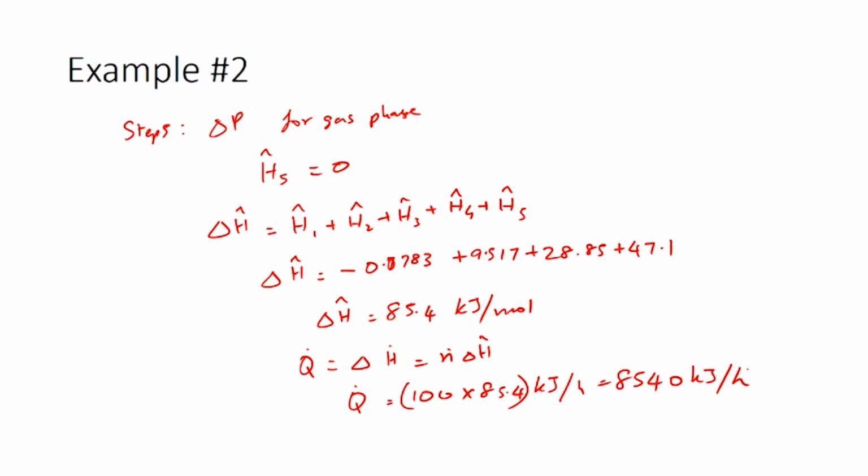In this calculation, one thing you would have seen is that the first step, V cap delta P, the change in enthalpy due to change in pressure for a liquid, was very small compared to all other enthalpy changes. We had 4 processes where we accounted for change in enthalpy; for the last one we assumed ideal gas behavior and calculated the change in enthalpy to be 0.